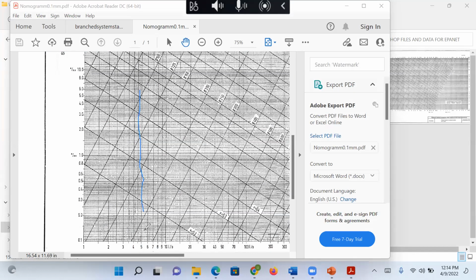I'll go down. 0.5 slope, if you convert the percentage, is this. Then you see it's giving me 100 mm. The other pipe is about 80. So anything between 80 and 100 will do it, but the law says you take the biggest one. So the bigger one, or the closest one to this, is this pipe, and this one is a 100 mm diameter pipe.